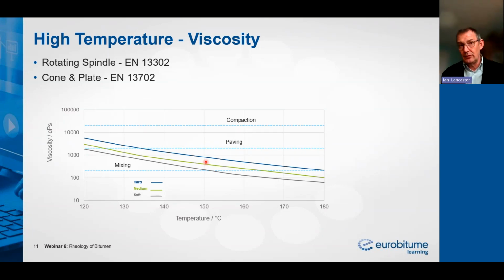So it's really important that we understand from a viscosity slash rheology perspective the relationship between viscosity and temperature, because it defines everything that we do.